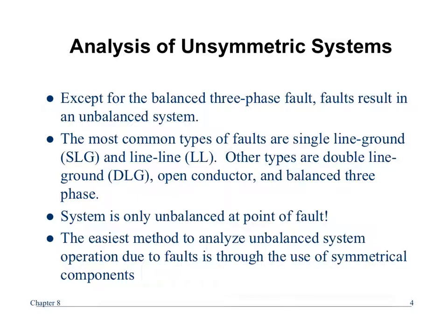Okay, let's get started. So we're continuing our discussion on analyzing non-symmetrical systems, and we talked about in the last class the concept of grounding, right? And again, that's a very important topic because grounding of systems is going to determine how much ground fault current you have, and will also determine the amount of damage your system can receive. So if you can, you would try to insert some sort of a ground impedance to limit the ground fault.